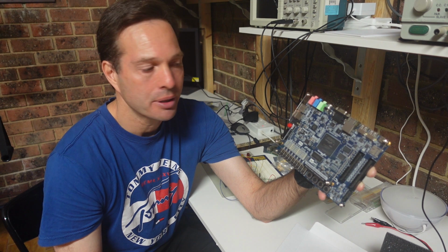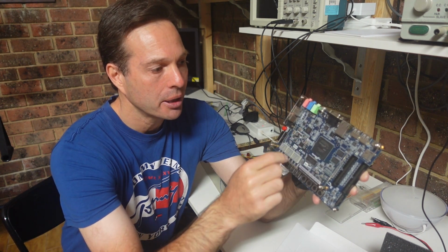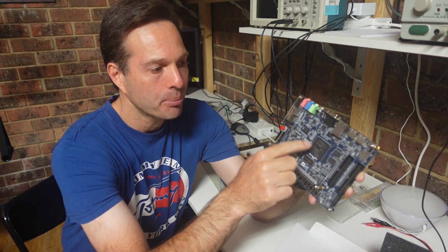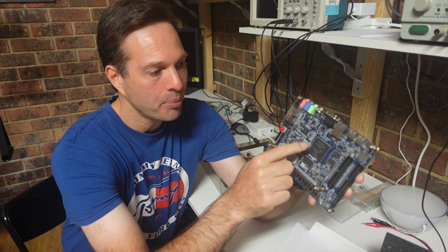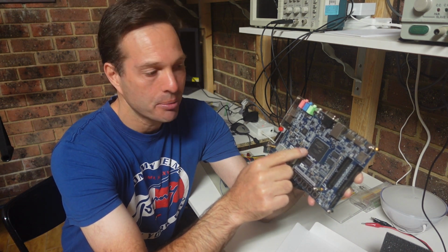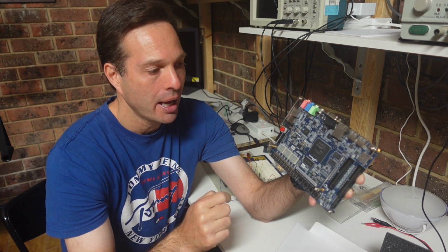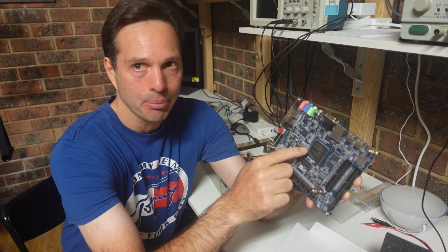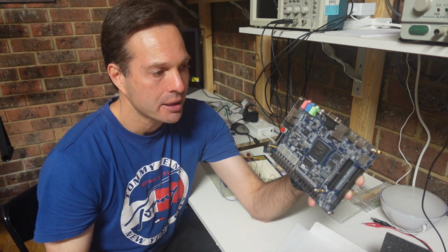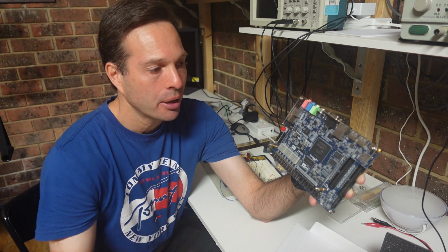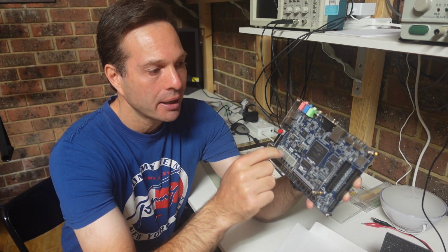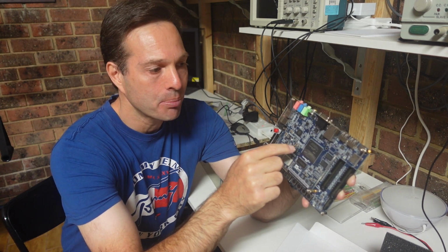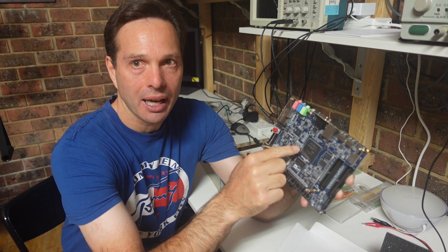Now, the way that happens is that on this development board, someone's already physically connected these buttons and LEDs to the different pins of the FPGA. This FPGA has got hundreds of pins. You'll be surprised how many pins it has on its bottom. And because this push button is already connected to a particular pin, all we can do is tell the software Quartus that once we've designed our circuit, this input that we've described in our circuit, we want it connected to a particular pin on this FPGA.